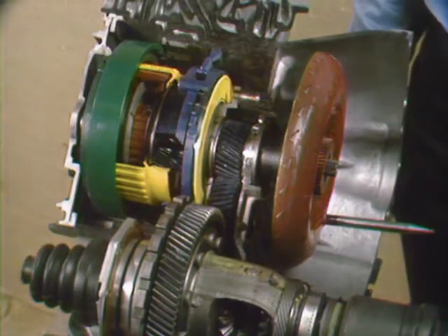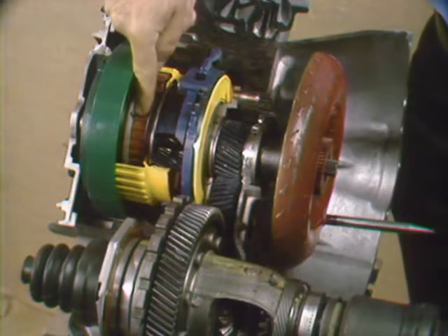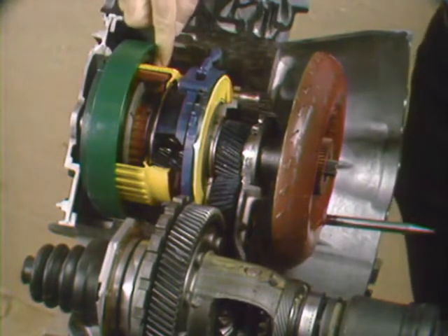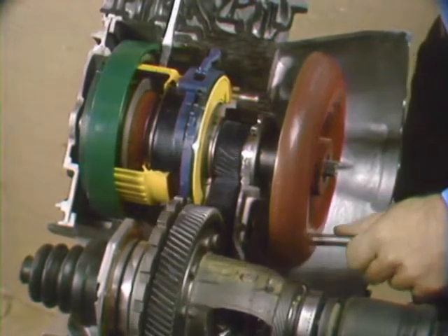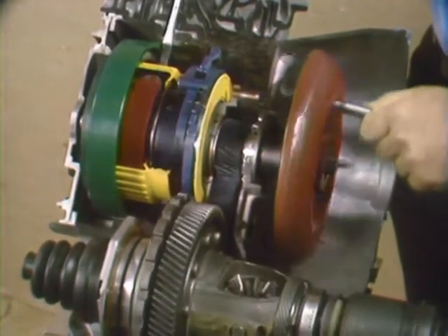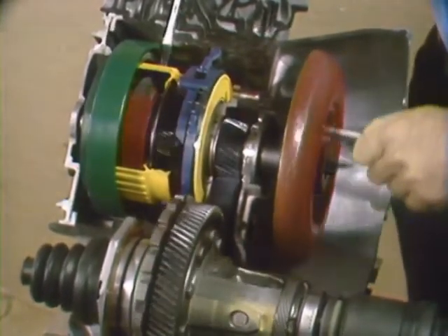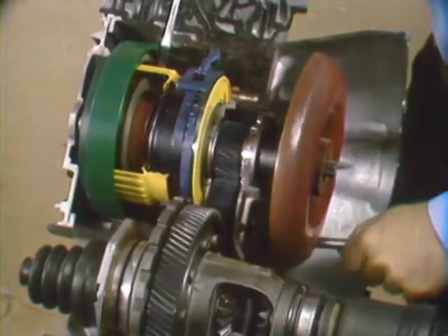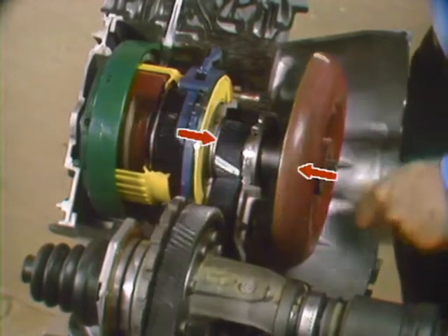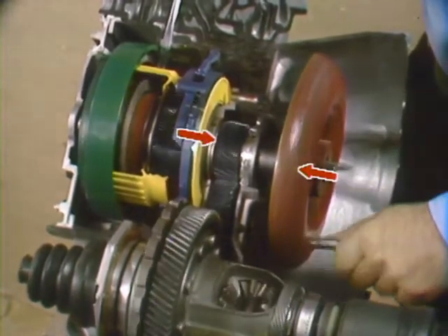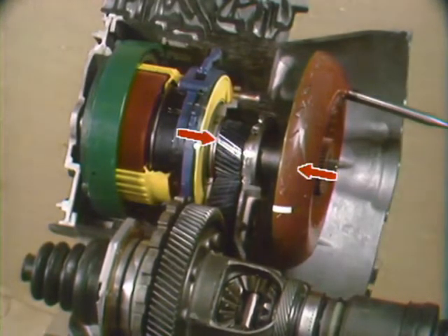Now, Joe has set up the cutaway for reverse gear. The direct clutch is applied. The ring gear is held stationary by the reverse clutch, so he'll hold it as he turns the turbine and turbine shaft. Watch the action. The turbine, splitter sun gear, and turbine shaft are all turning clockwise, but the planet carrier and final drive input gear are turning counterclockwise. Watch the marks and the gear reduction of 2 to 1. 1 turn of the turbine, and almost 2 turns of the turbine to 1 turn of the final drive input gear.